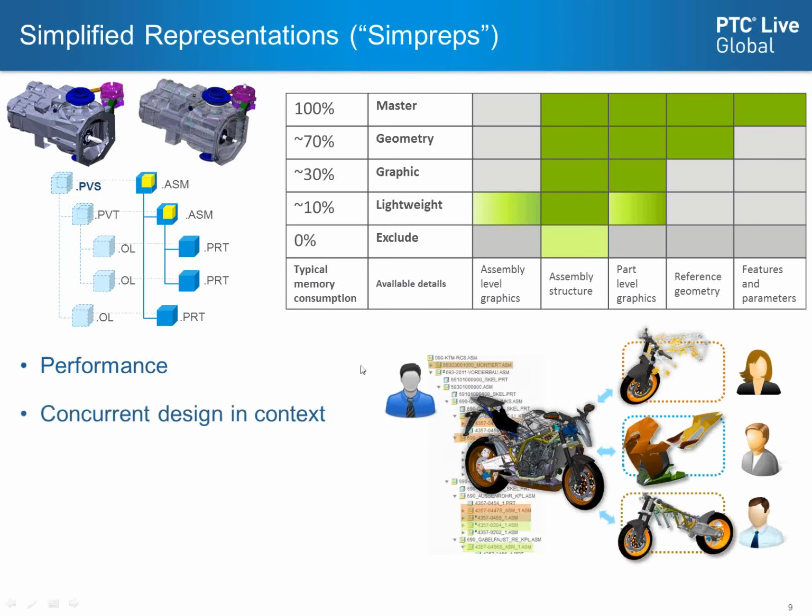So other uses of simpreps also, as I mentioned earlier, are the concurrent design context. Whether you use external simplified reps or open subsets, different users can access and filter different contexts of the designs that are relevant for their own design task. So they never need to load the entire assembly into session. They can work in their context that is relevant for their area, while the integrator can always get the top-level view and see how the assembly is changing and comes to life.